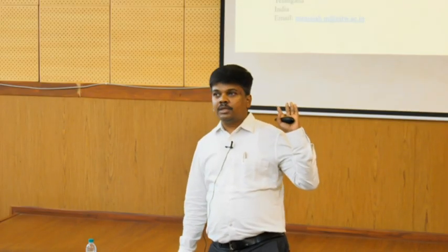But related to my talk, I am giving you only the important aspects of the powders and the gas, because gas is also a feedstock. We need to purge the gas for the entire PBF systems, or in the DED systems we need to protect the beads. That is the protecting gas we are using, or even the carrier gas for powder flow. Argon is for titanium or more reactive materials, and for stainless steel or ferrous-based materials we use nitrogen, and in some cases we use helium as a protecting medium.